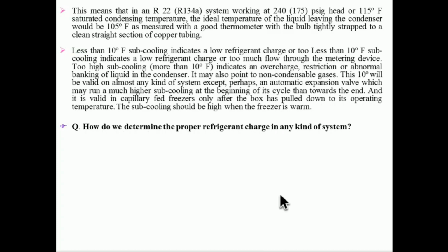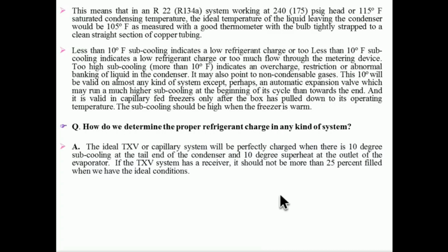How do we determine the proper refrigerant charge in any kind of system? Here again, whether it's a TXV, capillary, or other metering device, generally we keep an air conditioning application around 10 degree Fahrenheit superheat, and if it is a cold room or other application, we go around 6 to 8 degrees. And of course, if it is low temperature, people know it's around 4 to 6 degrees.